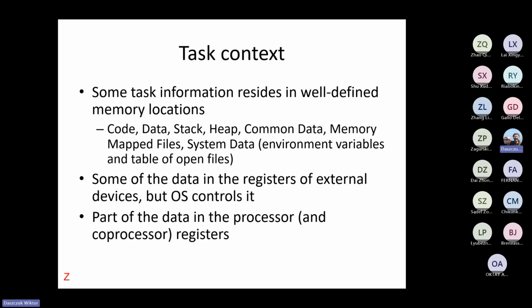The task context can be understood as the entire set of entities required to run this task, like the memory pool assigned to the task, some devices, maybe virtual resources, and in a detailed view, we call the context only the registers, only that part that must be stored when we switch between tasks.